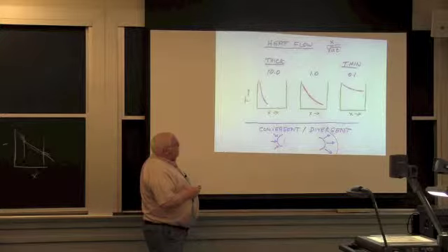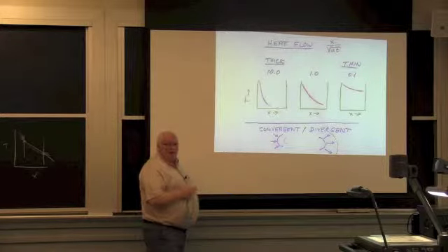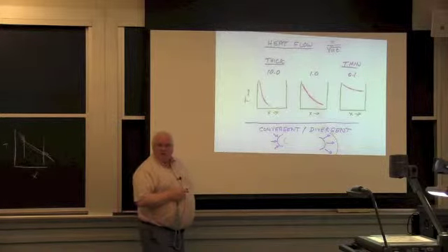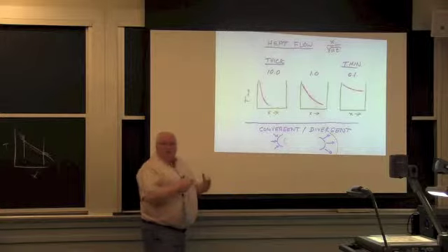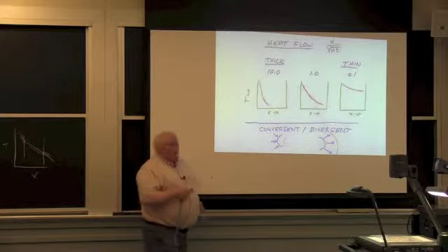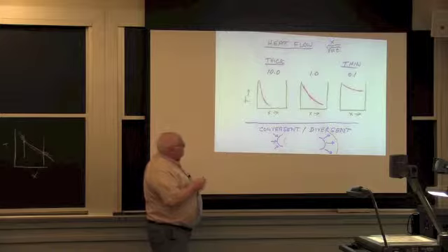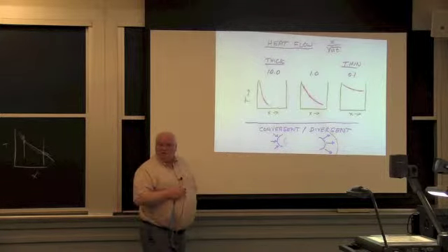Anyway, in a thick film situation, or a thick solution, basically the thing is so thick that the heat coming in doesn't get anywhere near the other edge, okay? And so you can just treat it as an infinitely thick solution, and you can use this number to figure out approximately the distance the heat flows into the material.